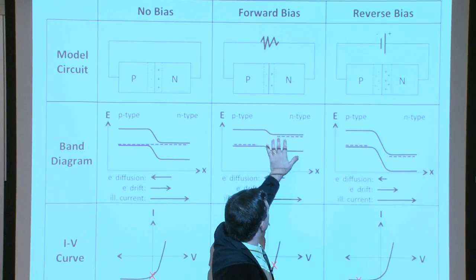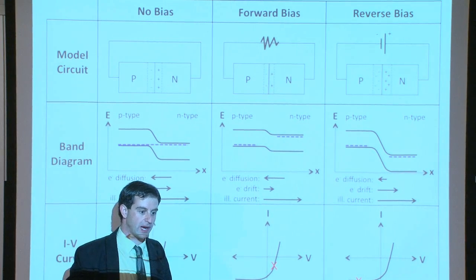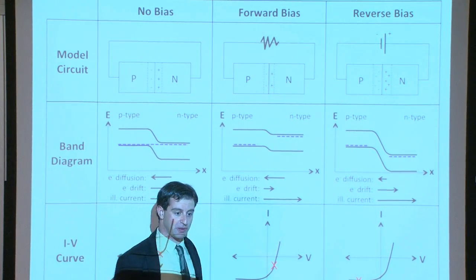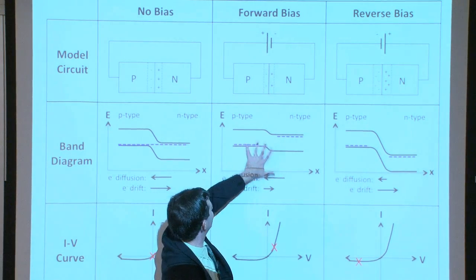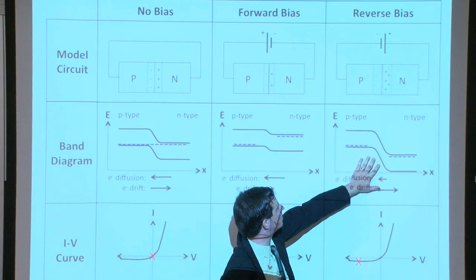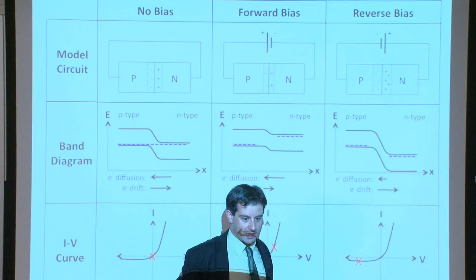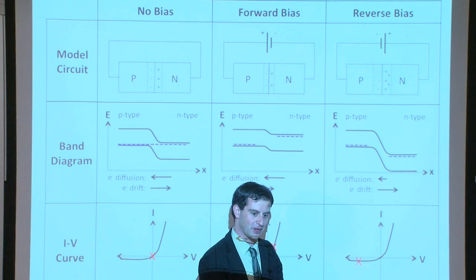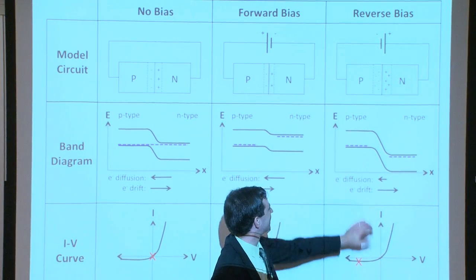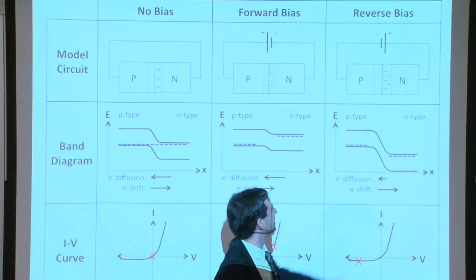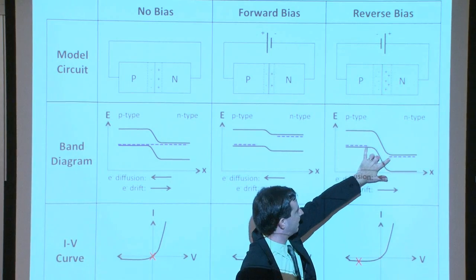What you could do, though, is have a bunch of solar cells connected in series with this one that are producing forward power. You could shade this device, and then power could be flowing backward through it. In other words, it could be in the dark and in a reverse bias condition just because of the way the other solar cells around it are behaving. If you have a shaded solar cell, for example, in a module, so imagine a seagull lands and covers up one of the cells, that will be under reverse bias, and that could present problems if the solar cell can't withstand the reverse bias.